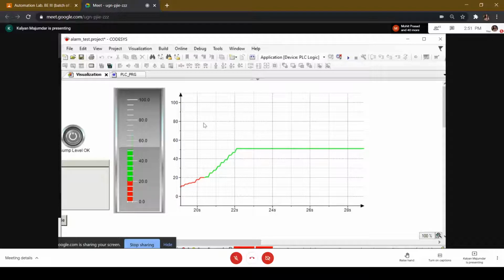So whenever something goes wrong, you can look back into the historical data on this particular graph. You can just set the time: I want the data from this date, this time to this date, this time. It calls back the data from the storage device, from the server, and displays it on the graph so you can see what exactly happened at that particular point of time and what led to the malfunction or whatever problems you have.